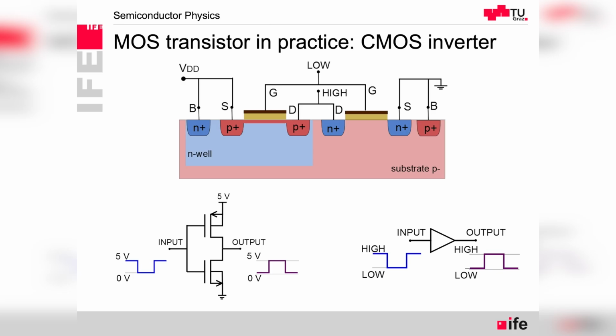Hopefully, for CMOS, the threshold voltage is in the range of sub 1 volt. The N-channel is fully on, so it's pulling the output to ground, and typically in CMOS stages the next stage is just a capacitive load. It doesn't have to provide drive current except for leakage current for the next stage. So there is not much stopping the NMOS transistor from pulling it down, except possibly the PMOS. But let's see what happens with the P-channel transistor.